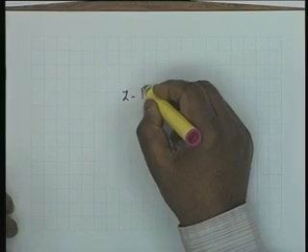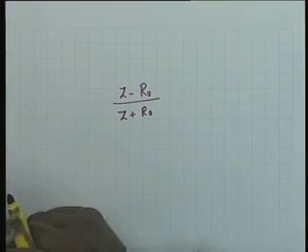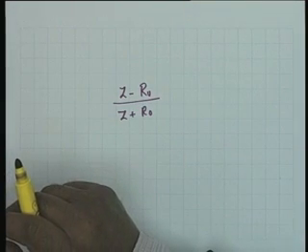If not, why not? When resistance is negative, that is perfectly alright. The parameter is equal to minus R naught. So the input impedance is the negative of the reference impedance. Just a minute. What you are saying is Z minus R0 divided by Z plus R0, where Z is equal to minus R0. Okay. So it is possible. They don't exist at that time. Why not?